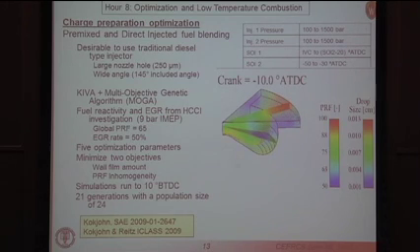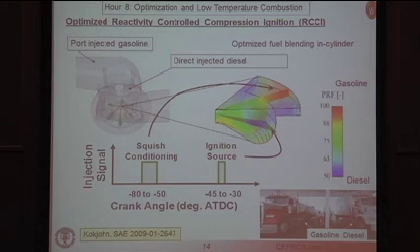And so what we expect is going to happen is when we compress this mixture, the diesel will ignite first, and we'll have combustion occurring progressively because now we have a premixed mixture. We're not relying on flame propagation. We're relying only on chemical kinetics, but it's going to be phased such that the duration of combustion is determined by the gradient of PRF in the chamber.